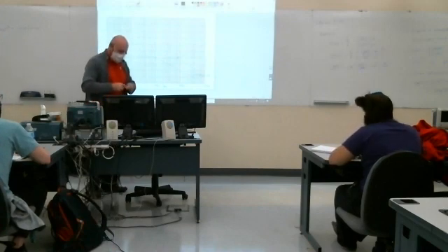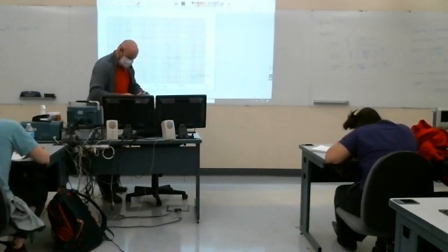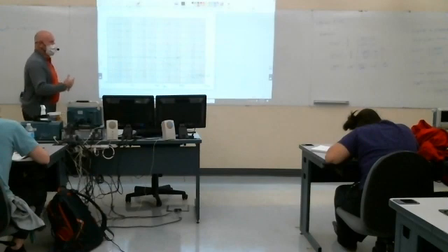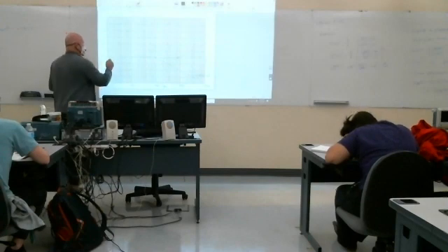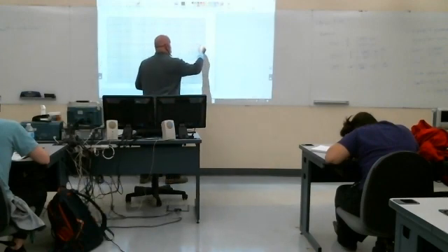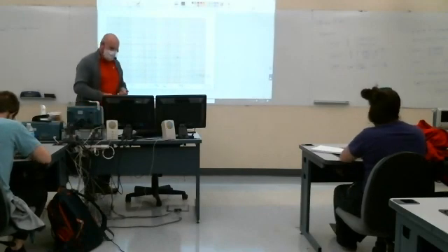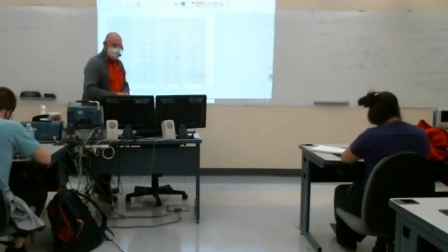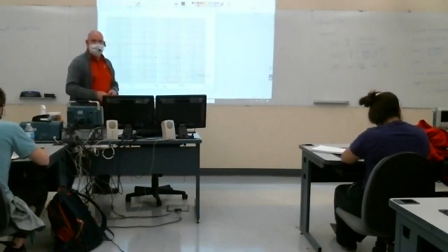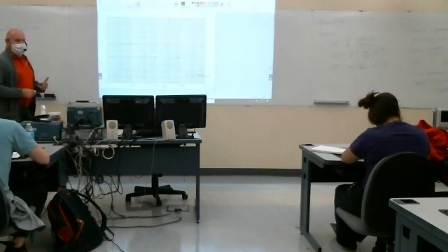And then the other piece here is my constant, the 20 log of 10. Now it's 20 dB, and that is 20 dB forever. Okay. The last piece is to graphically add these things together.